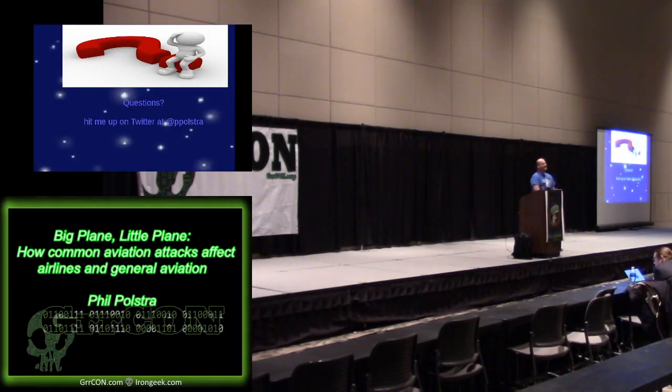Okay, that's a good question. And the answer is no, for a couple reasons. Number one, if I send in a new flight plan using ACARS, it has to be reviewed and manually accepted by the pilot. So the pilot has to approve the change. It's not like, oh, here's a new flight plan, and then, woo, off it goes.